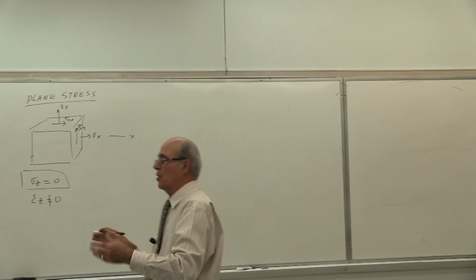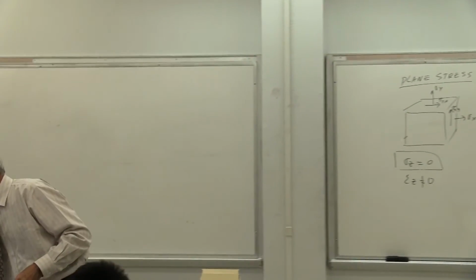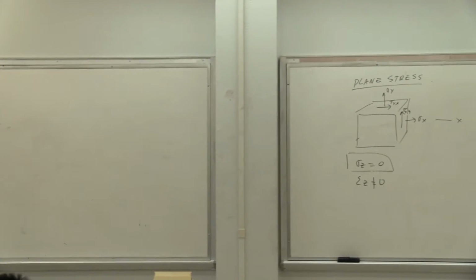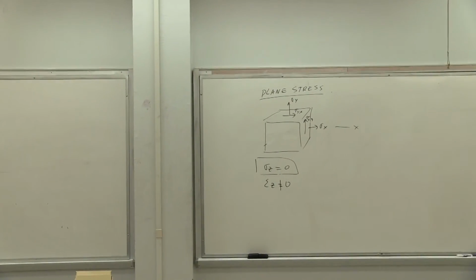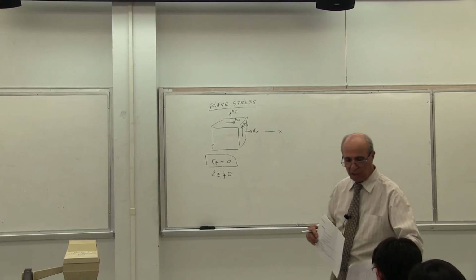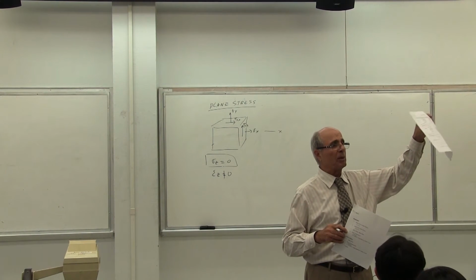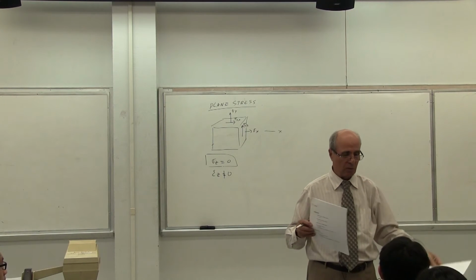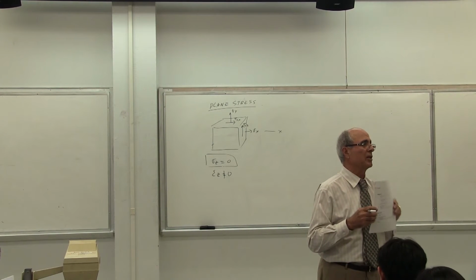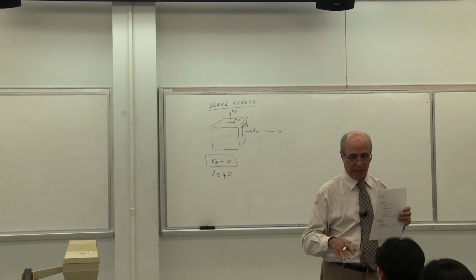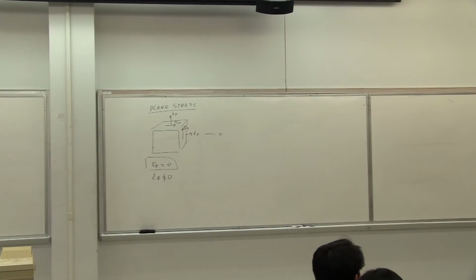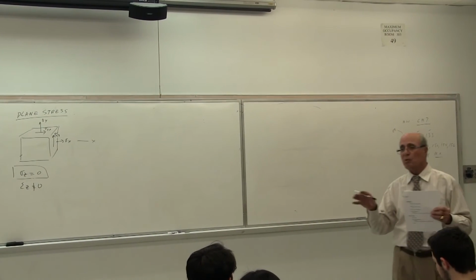Yes? And then finally, question number 3. Let's just find the absolute maximum. Absolute maximum means you have to go not through one circle; you have to go through three circles. Yes or no? Some of you even disregard that in totality. Absolute maximum shear strain means there are always three circles, not two circles. The meaning is there. When I say epsilon, it means go out of plane. Yes or no?